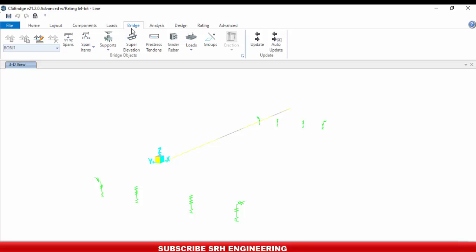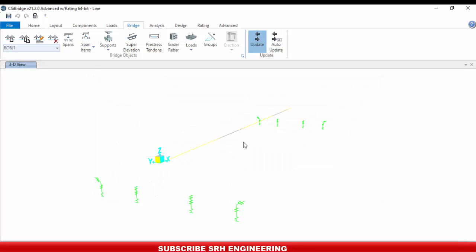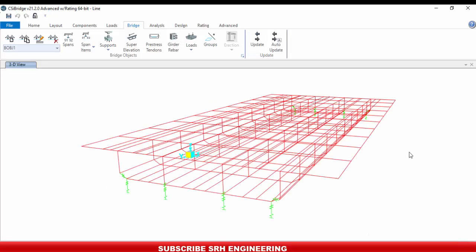If I go to the bridge here, I need to unlock this model. If I go to update, then you can see here, I can convert right now. I have this spine model using frame. Now I can convert it into an area model. I can keep the preference the same. If I click OK, after some time this same model is converted into the area model.